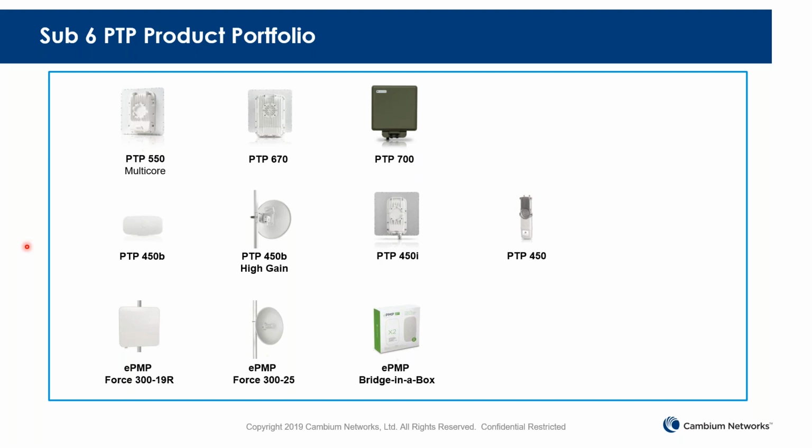The 820C HP is the outdoor version, and the RFU-A has two variations as well, RFU-AE and RFU-AXP. They're two different power versions. They're all suitable for long range, and you basically go with the link planner. You can choose different radios to see what range you can get.